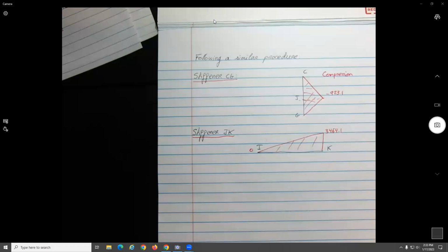What happens if you decide to put another bar in the other direction? Now the problem is statically indeterminate. But is it safer than the first one? It has 2 members instead of 1 going across. So let's say you do your analysis for the structure with only 1 member going across, and you find out that your structure is safe. Can you make the assumption that the structure will be safe if you put 2 bars in the middle?